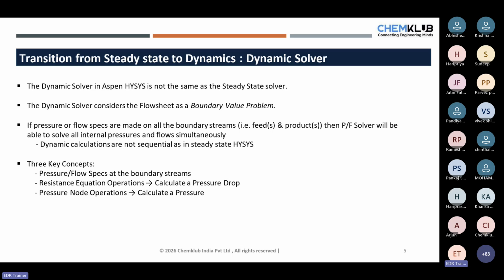So there is no accumulation considered. Whatever comes in should come out. Say you have a distillation column, which is a complex unit operation. The feed in is equal to the feeds going out of that column. They should match, and finally in minus out should equal zero, which means there is no accumulation. Also, time is not considered. This is the steady state operation: if you put this much in, this much is going to come out.